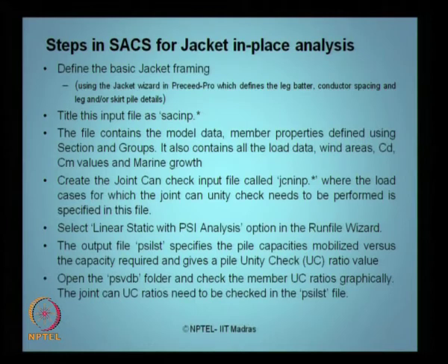So, once you open the PSV DB folder, which is the name of the folder automatically generated, check the member or the members for the unity check ratios graphically, because graphically it will show whether the member has exceeded the unity check ratio exactly.